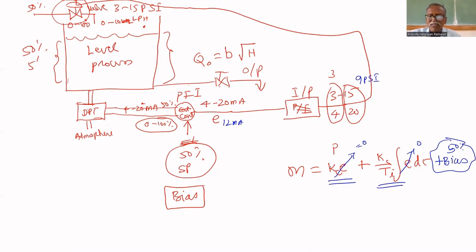Here I put some constant Kc multiplied by error. Here I put Kc by Ti, integral of E of t. These constants vary depending upon the process. For that, I will give one example. Today, I am driving an old car. Same slope while going from here to Marakanam. Some speed is changing, that's why I'm giving additional acceleration, so speed is maintained at 60.